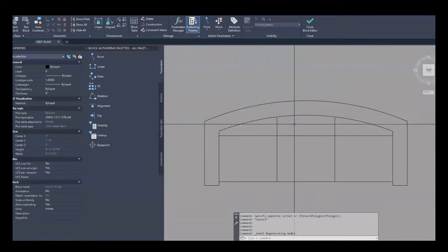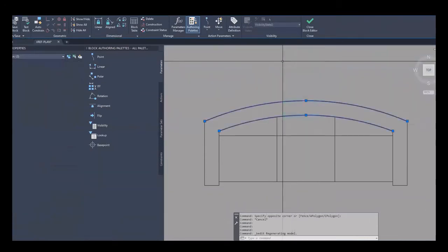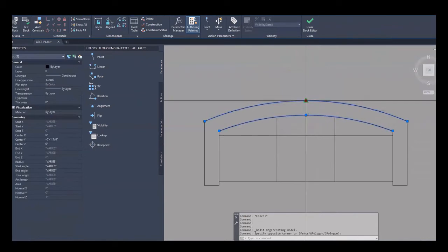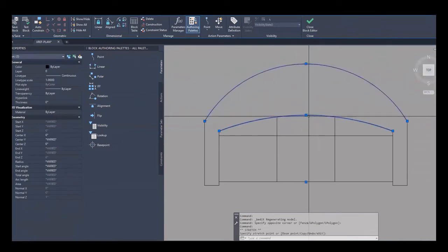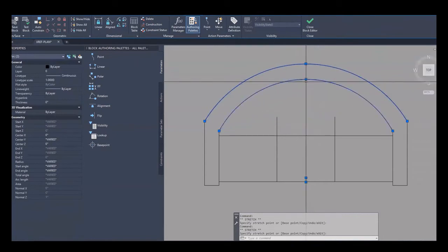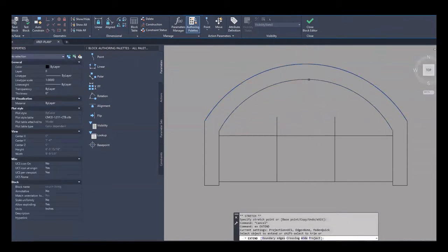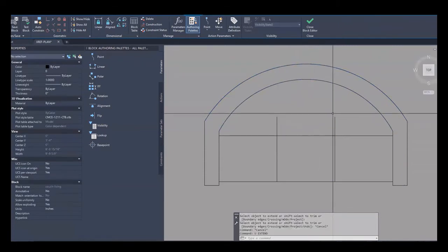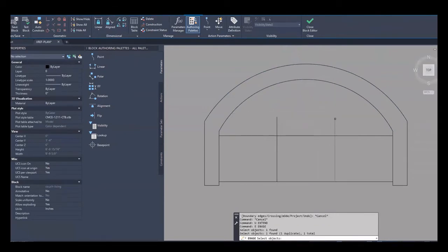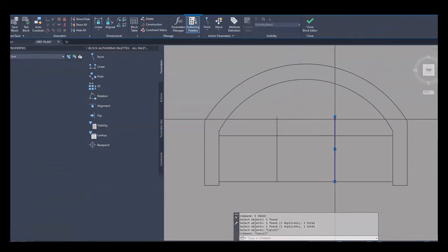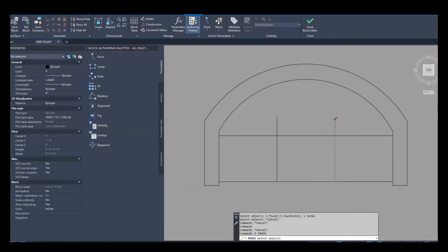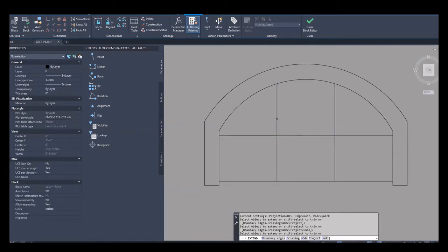If you notice, the screen changed to this gray background, and the ribbon changed a little bit as well. From here, it's basically isolating the block which you want to edit. Here I can edit the block however I choose. I can add lines, modify the lines, or erase lines. Here I'm just manipulating a few lines on this block to make it look different from the original, and you'll see how that works in a second. I'm just extending some lines to make sure that the drawing is complete, and that it looks drastically different than what it is.